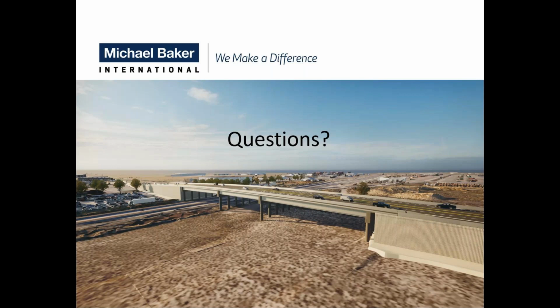Okay, and then did you consider a fix at top as well as pushover analysis? Sorry, no. Did the column consider fix at top as well as pushover analysis? Okay, in the longitudinal direction, it was not. It was essentially at the top of the cap, at the bottom of the girders. It was pinned, but in the transverse direction, the columns had the double curvature, so it was more fixed at the tops of the columns. And yes, we had looked at that, designed it that way.